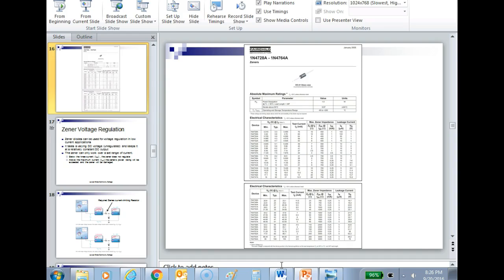Because they're dynamic devices. When you start dealing with dynamic devices, you're worried about one guy stealing the show. So that happens a lot. If these guys are not exactly the same, and the odds are they're not, we have that problem with transistors in parallel and stuff like that. You would think you'd be okay. You think you'd get twice as much current. You don't, because usually one of them tries to steal the show, and he'll burn up, and then it burns up the other. But you can do things with transistors. So what I would do is I would just find a Zener that could handle what I needed to handle.